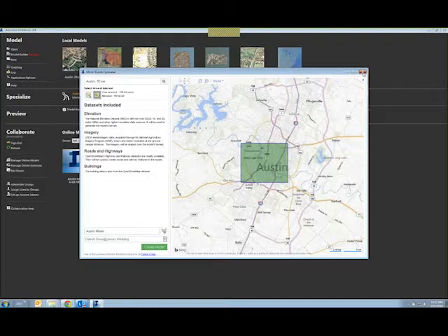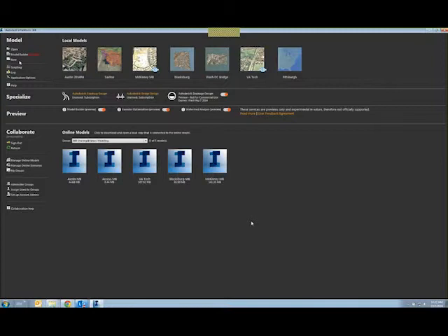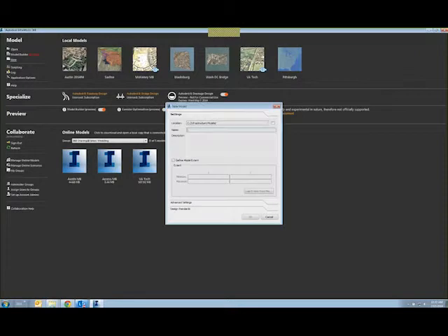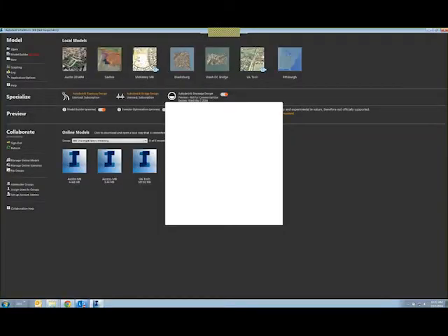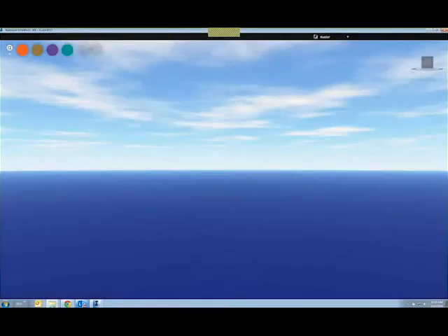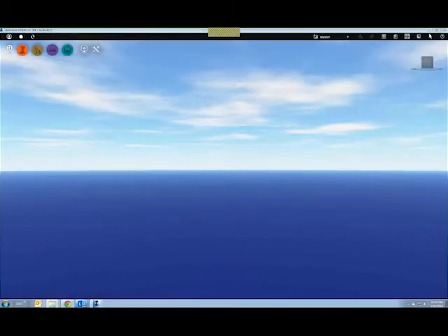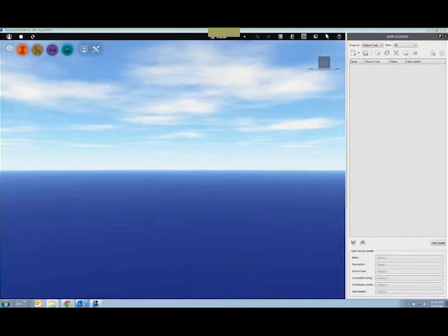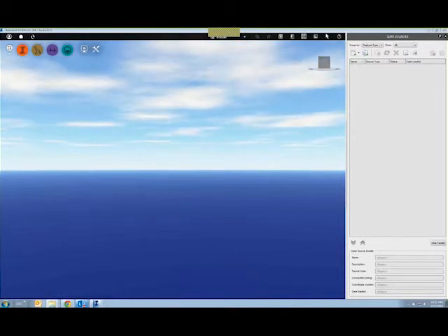So I'm going to close this now, and let's take a look at building a model, again, from some of that data. And I'm going to just simply create, again, my Austin model, and we'll start with blue skies. So today is the 13th. And when we start InfraWorks, it simply starts with a blue sky scenario, and you can start dragging and dropping information. Now, for me, I always like to start with a little bit of terrain. So I'm going to actually use the elevation data that I did get from the national map, downloaded, unzipped, and I simply drag and drop that data